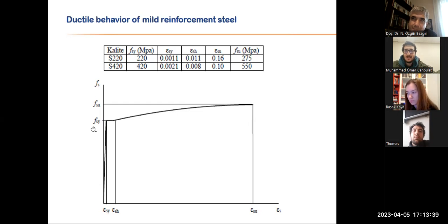But for example, for an R value of 8, if an earthquake that is 8 times what the structure is designed for acts on it, do we exactly know where it is going to be? Because this is a very nonlinear part. Can we just multiply? Can we say, okay, we're going to be somewhere over here? Is it for sure? Or will I be able to hold on to these rebars to elongate them this much, up to that point?